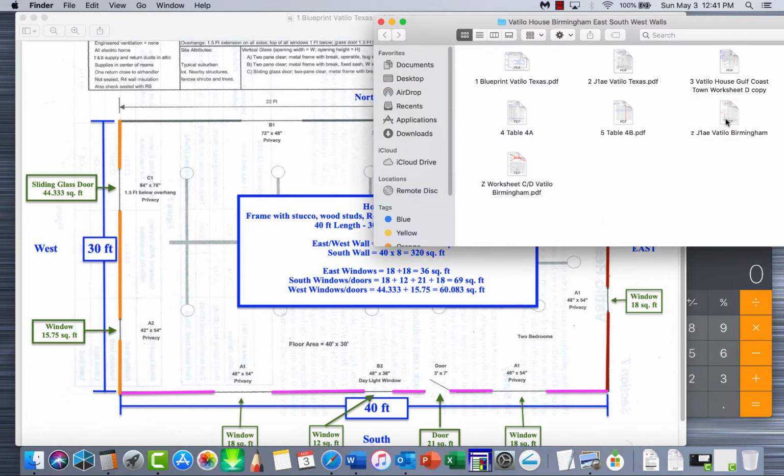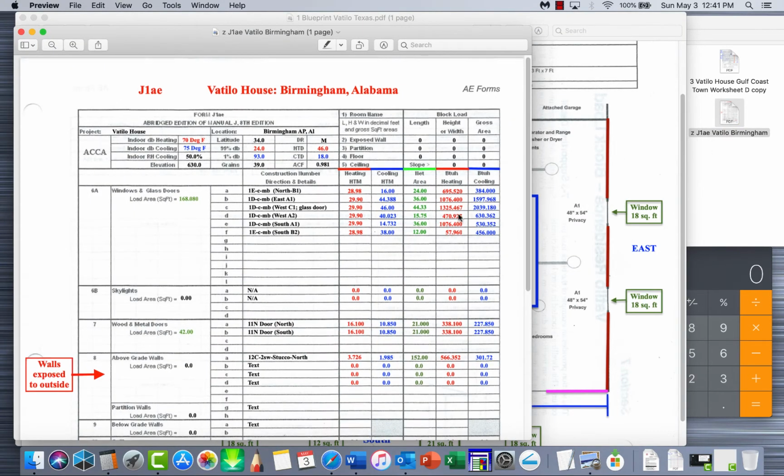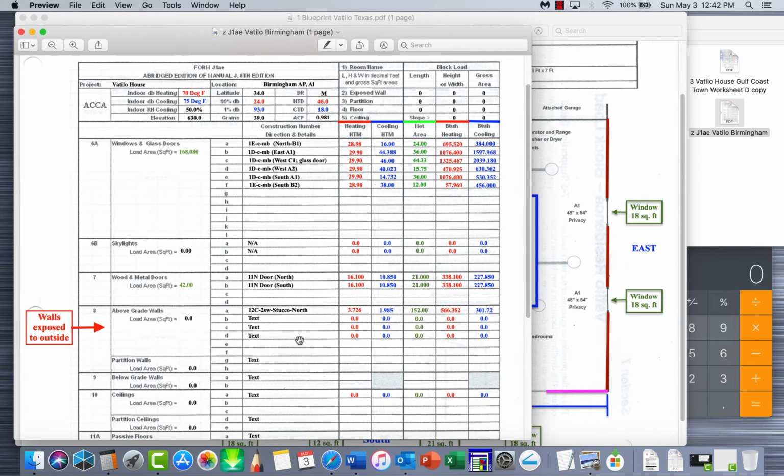So let's bring up where we left off here in Birmingham, Alabama. And as you can see, we got the north wall done. Now the good thing about walls on houses, typically, unless it's an add-on or it has many different types of designs to it, like it's not your typical box type house, is that most of the walls, the construction is going to be identical, because when they put the walls up on a wood frame construction home, it pretty much goes up all at the same time. Same insulation in all the walls, same interior in a lot of the walls, and same exterior. Like if the house is all vinyl, it's going to be completely wrapped in vinyl. Not always true. You could have a brick facade here, and some type of decorative change to the exterior, so that it gives it a different look. But typically on most of your homes, this is how they're going to be.